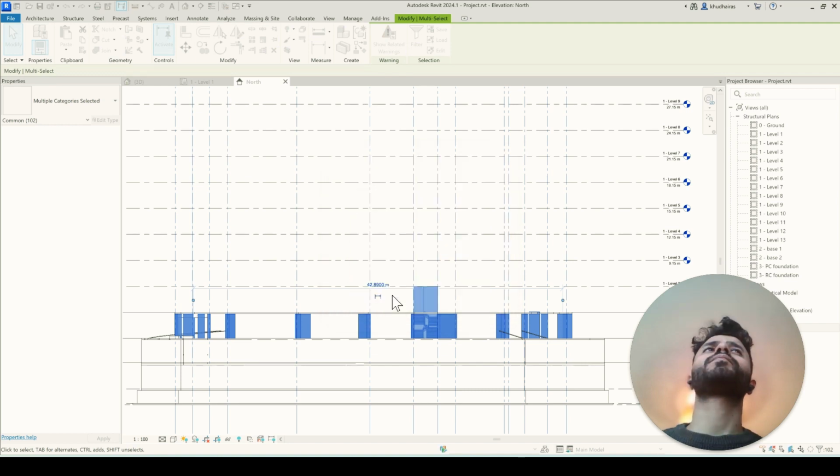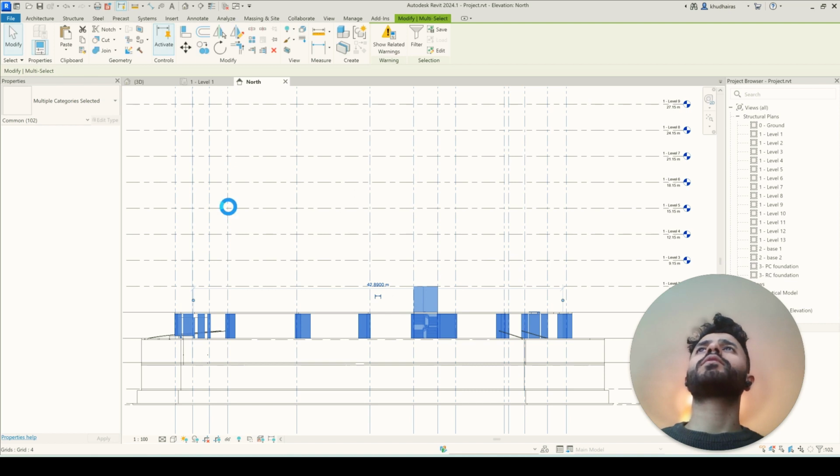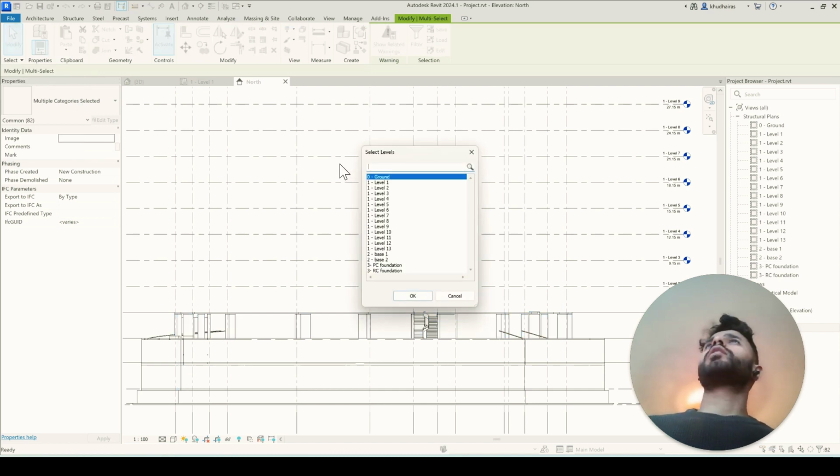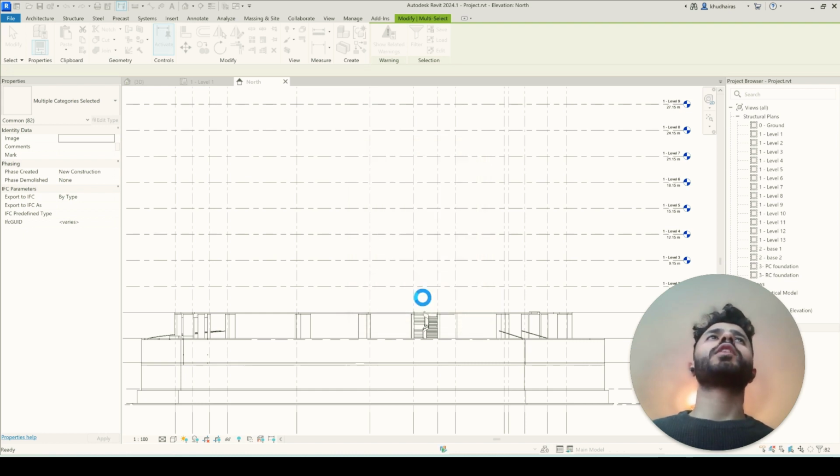Okay. And this will select the walls. So we do copy, then align it to different levels. So for example, we are on the first floor. So this is basement 2, 1, ground, first floor. So I'm going to 2, 3, 4, 5. So the software will copy this to the different floors, and they should be shown here on different levels now. So let's have a look.